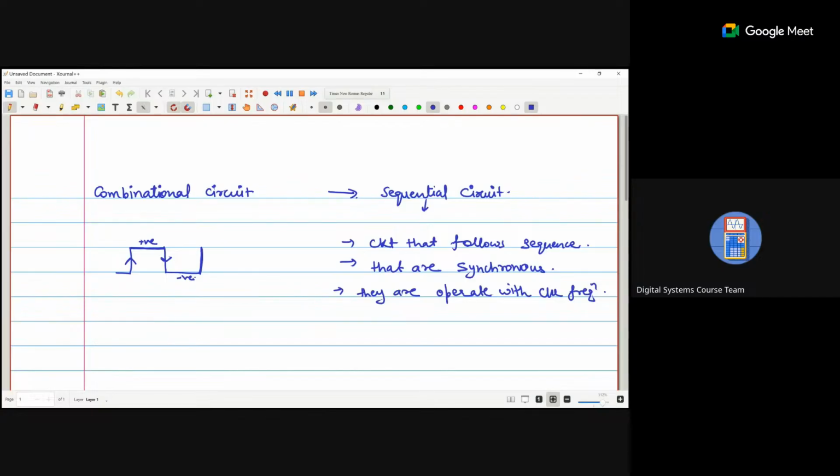Now, if we are talking about the rising edge or the falling edge, the time taken for the edge is very small. Ideally it is zero, but in a real system the transition from zero to one takes some time, in picoseconds or less.